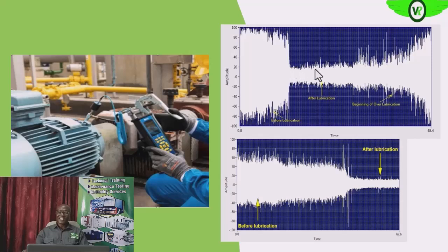So this is the point to stop greasing, because when you continue, you see that the vibration level, now you have over greased, the ultrasonic level will go up again. Are you getting? This is the area where you start causing overheat, or heating up of the bearing. So we do not want that. Once it comes down and we see that it's a little bit steady down, then we can stop greasing. That is the optimal point, or the point to stop.